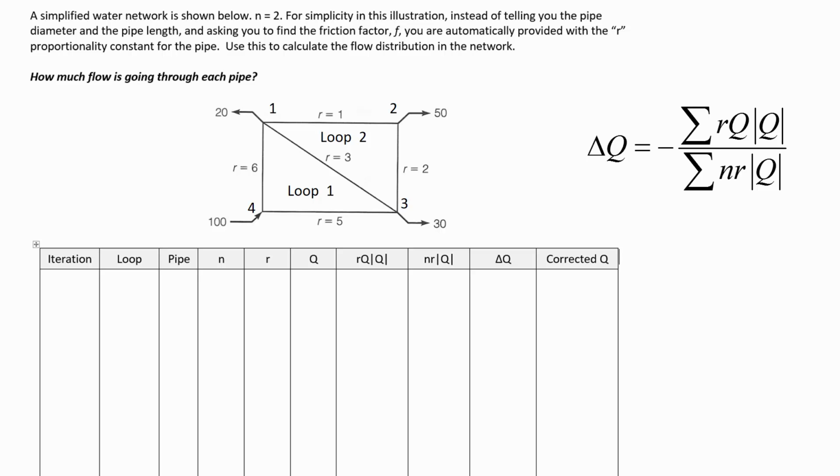Okay? And the flow rates. We're going to do a similar thing as before, looking at our flow balance sketch. We've already defined our first flow balance. I see the beginnings of a question in the back. Ah, brilliant. Yes, you do. So he's asking for pipe 1-3, do we use our original guess value of the flow rate, or do we use the new and improved version, the corrected Q? We use our corrected Q.